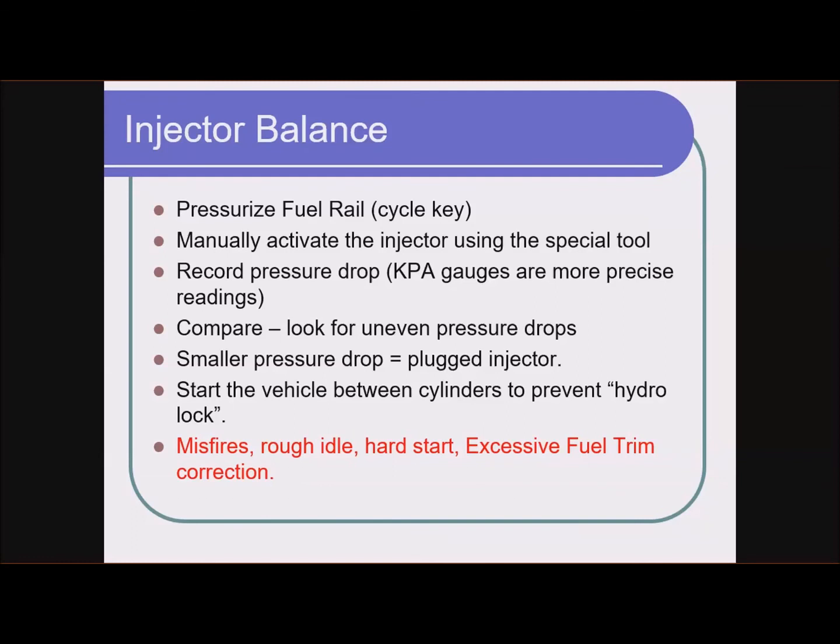When that injector fires, you'll be able to see a pressure drop in the fuel rail as fuel flows out of the rail through that injector into the intake manifold. So the idea is you do this on every fuel injector and you compare the pressure drop on each injector with all the other injectors.